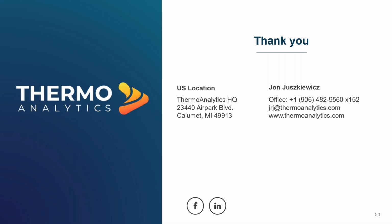Cotherm supports any type of export, whether that be the local heat transfer coefficient, a reference heat transfer coefficient, or the Y+ method as you've described. All of those will work just fine within this paradigm, but I'd suggest that we have a more detailed conversation about what physics are at play and what your meshing paradigms are before I give you a definite answer, but I'm sure we could use that method.